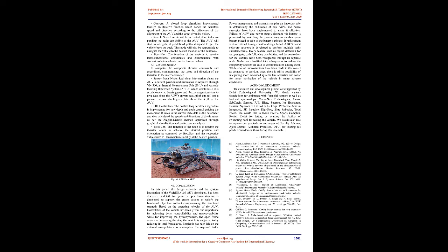The stack was designed as a hybrid topology implemented as ring topology within the topmost nodes. The stack is divided into modules. Software module: it processes the information received from the cameras, makes a decision according to the task selection, and forwards appropriate guide data to the next module. Navigation module: works on the guide data received and calculates the speed and the direction of the thrusters. Control module: this module gives appropriate commands to the actuators through the microcontroller and ensures stable movement through PID control.